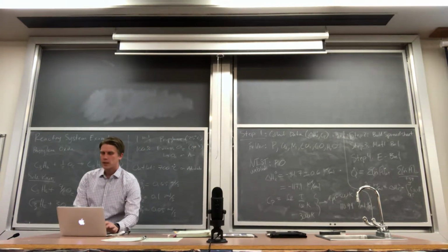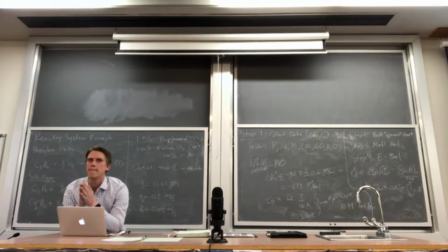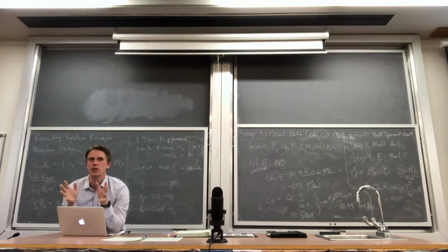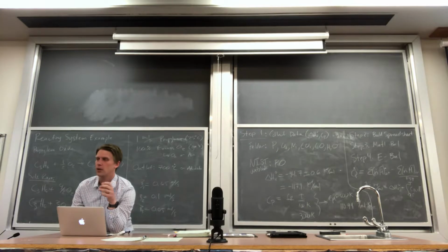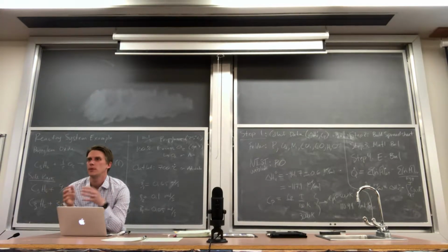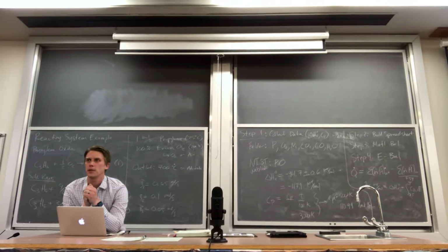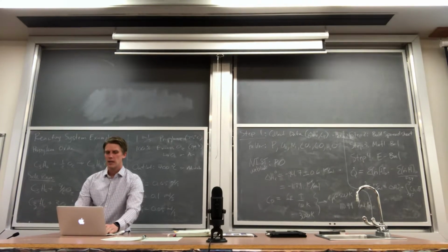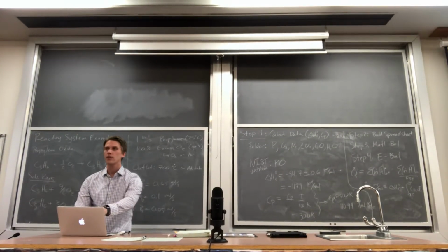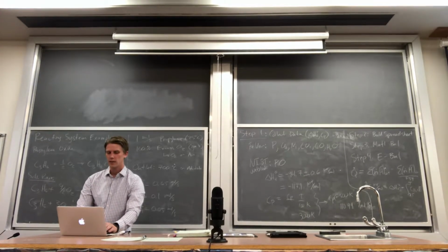Now, when I'm doing an energy balance, and this is something you may have to do for project part 2, you don't have to do an energy balance over a single unit operation. You can do an energy balance over an entire process. And if you were to do that, you might have different streams coming out in different phases of matter at different temperatures, in which case I should probably have added in a column here for the temperature outlet of each different material. But since this is just a single reactor, I kind of cut that corner and I just put one single location for the temperature. But every single one of these equations is the same equation. And it draws on having the fact that everything is organized nice and consistently.